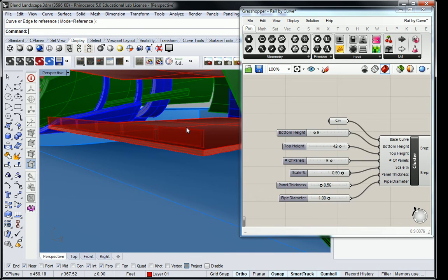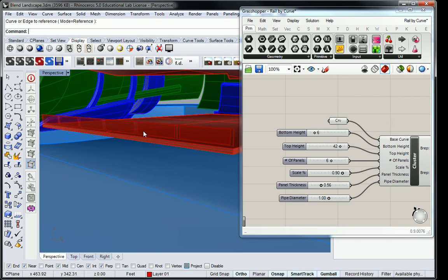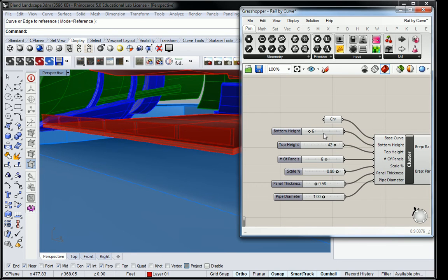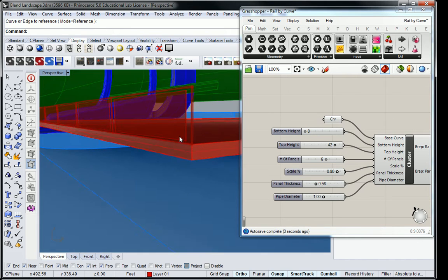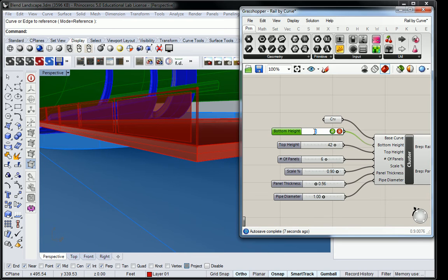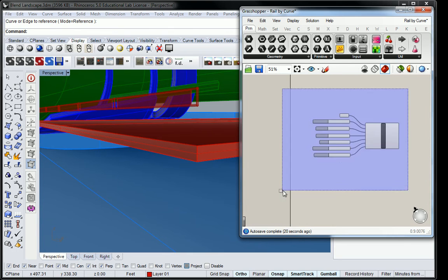I'm not going to get crazy with the Grasshopper definition, but very simply put, if you change these things, you can reduce the 6-inch offset at the bottom to be exactly flush with the bottom of your plane, or bump it back up to 6 inches and lift it up a little bit, or even go a little higher and make it 12 inches, or if you wanted to get a little crazy with it, you can go up to something like 30 inches and then make a copy of this thing,